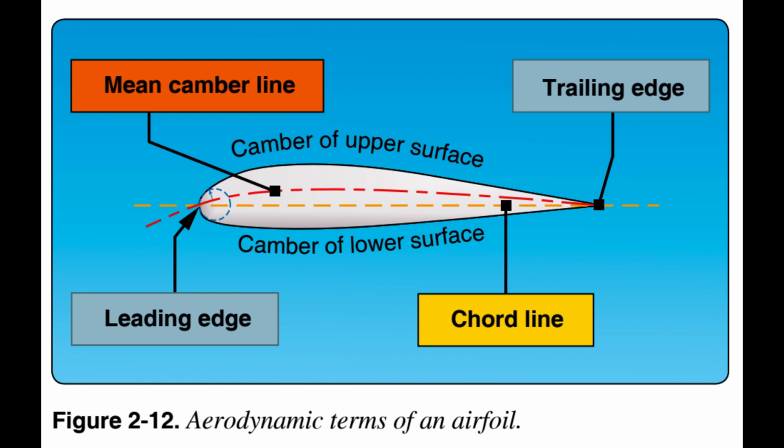5. Angle of incidence, AOI. The angle between the chord line of a blade and rotor hub. It is usually referred to as blade pitch angle. For fixed airfoils, such as vertical fins or elevators, angle of incidence is the angle between the chord line of the airfoil and a selected reference plane of the helicopter.